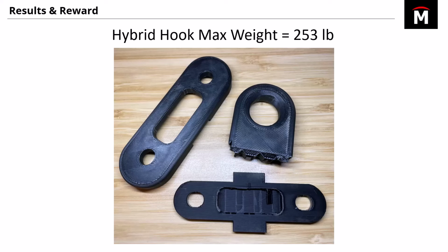With the hybrid hook, I was really happy to confirm that it was actually the strongest option when using the same basic print settings as a single part approach. But the failure did surprise me a little bit here as well. Although looking at it now, it makes a little bit more sense because one of the things we talked about was using fillets to reduce stress concentrations. And this was just a straight 90-degree edge here. So I'd be interested to know if filleting that edge would have made much of a difference.